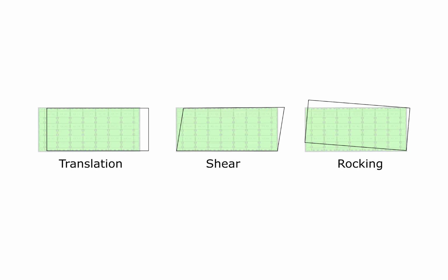From the capacity and rotation perspective of the wall, it doesn't matter too much, at least according to the literature review that I carried out. But I will link the paper in the video. You can see by yourself what is actually the effect of these assumptions. But for our WikiHouse wall, for the sake of simplicity, we will assume that the rocking point is going to be on the farther side of the wall.